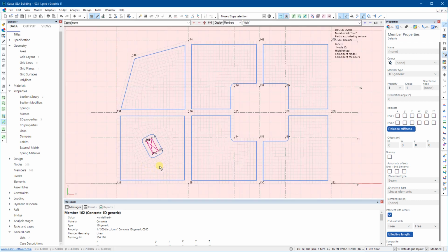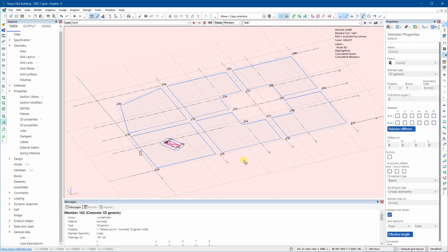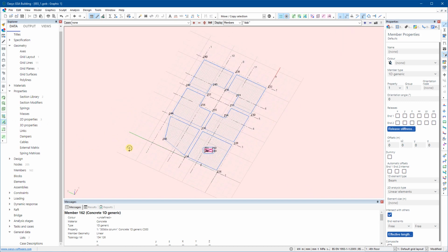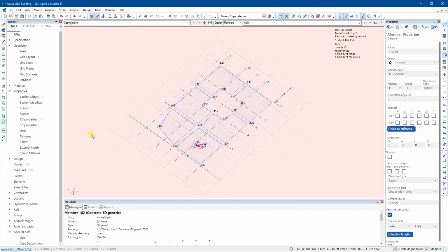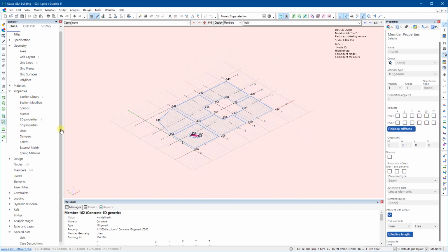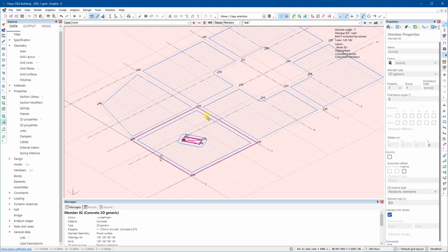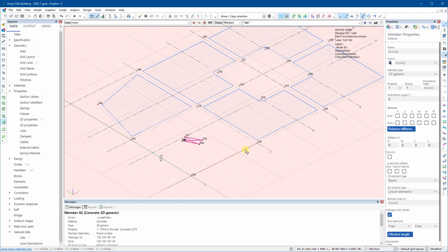Firstly, I'll start by selecting. If I turn the view, and I should have said, although I've got the member tool selected here, if I hold down Shift and my middle mouse button, it allows me to rotate. So I don't need to go to the rotate tool explicitly. So I want to select this first slab member there, and I'm going to come over to the right hand side and change the group number to 11. If I hit return, that's then assigned that.